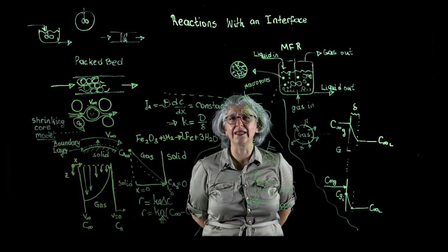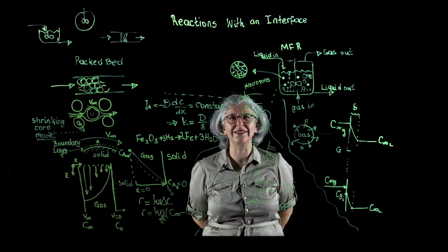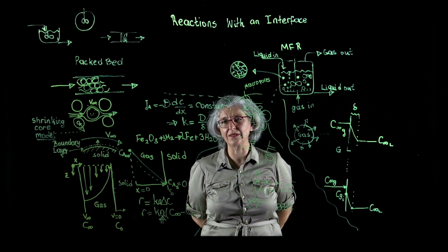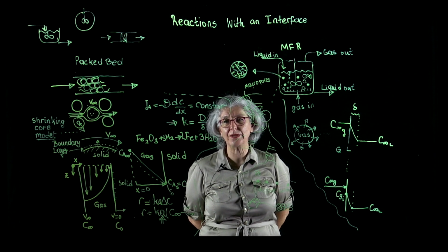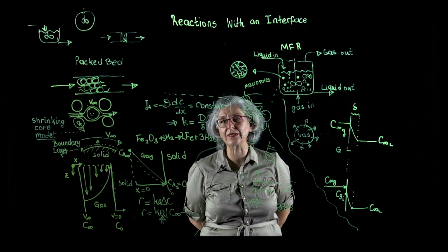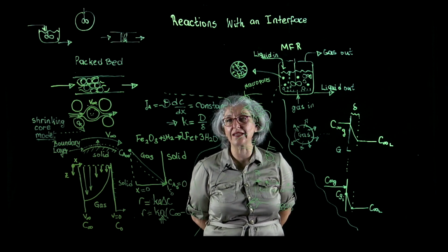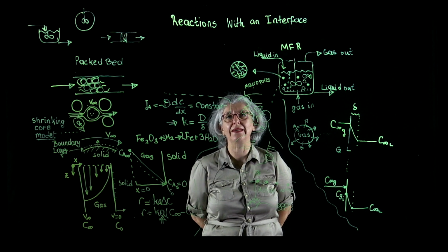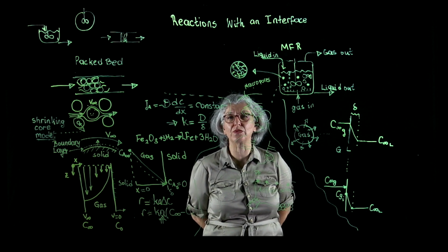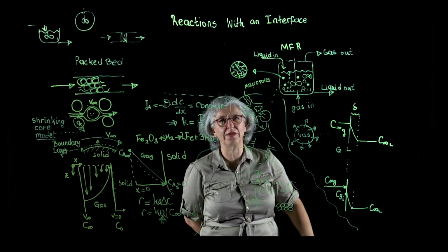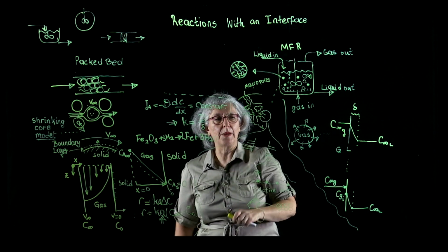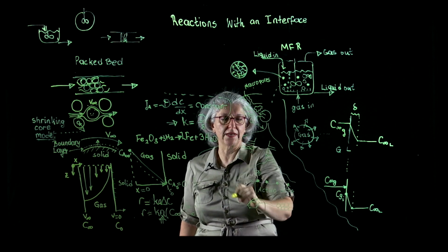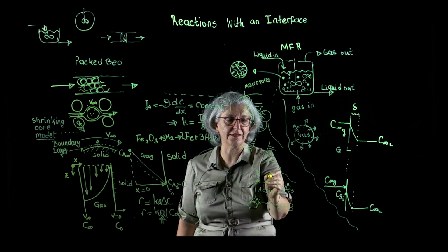The liquid that is filling the solid particle is no longer the bulk liquid. It is the liquid and the solid. It is subject to different constraints and conditions. And some of the liquid is really a stagnant liquid. Okay? And this gas molecule is moving through this stagnant liquid, bouncing off the walls until it arrives at an active site.